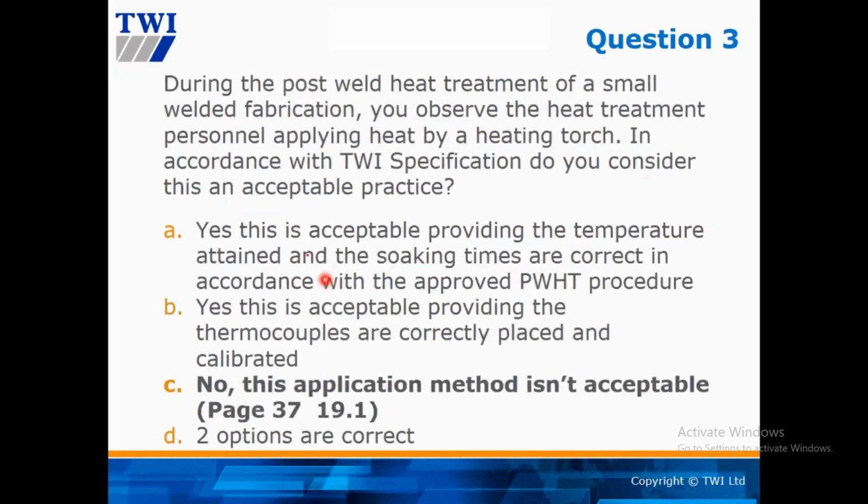Number 3. During post-weld heat treatment of a small welded fabrication, you observe heat treatment personnel applying heat by heating torch. In accordance with the spec, do you consider this an acceptable practice? So this guy applied heat treatment by using a torch.